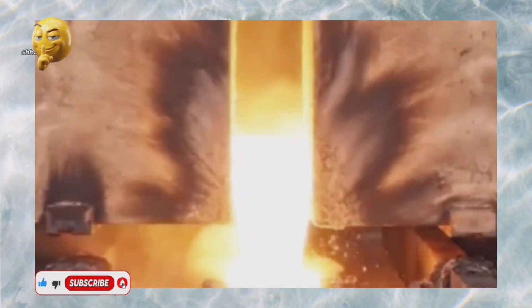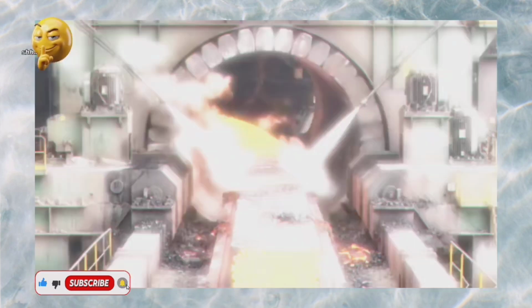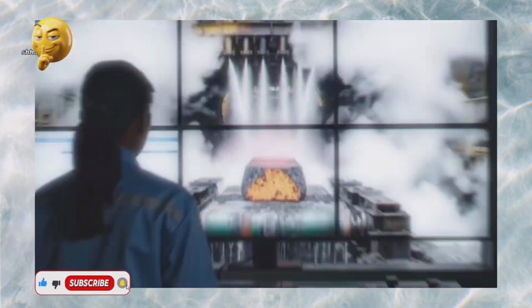Inside, temperatures exceed 2,000 degrees Celsius. Chemical reactions strip oxygen from the iron ore. Molten iron forms and flows to the bottom like liquid fire. Impurities combine with limestone to create slag, which floats above the iron. The result is hot metal, also called pig iron.